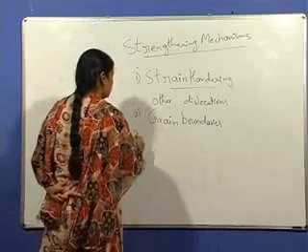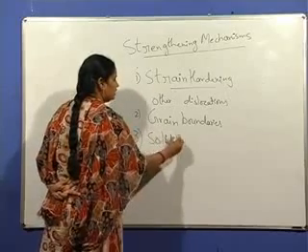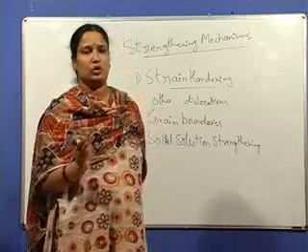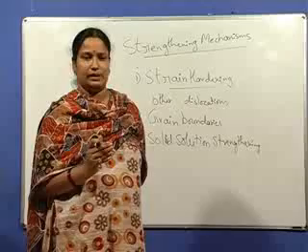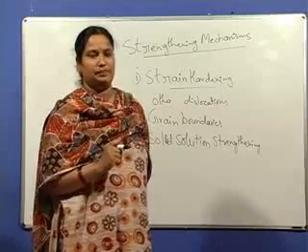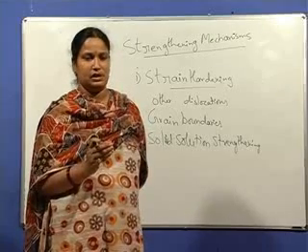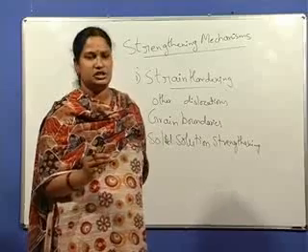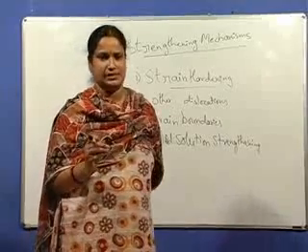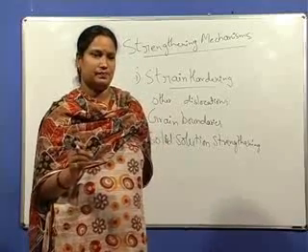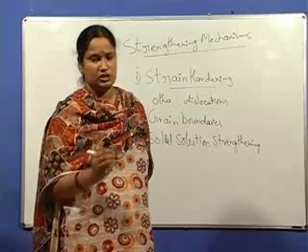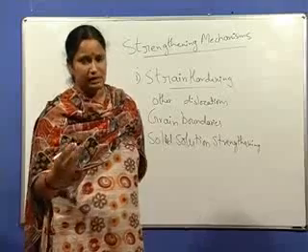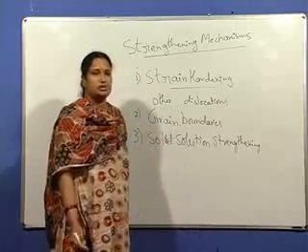Next, the third is solid solution strengthening. Solute atoms, both interstitial and substitutional, also contribute to strengthening. This was also discussed in yield point phenomena. The substitutional solute atoms move near the edge dislocation to reduce the strain energy, and interstitial solute atoms, which are much smaller in size, form Cottrell atmospheres. They occupy the positions below the edge dislocation. How they contribute to strengthening was also discussed. Still more explanation about solid solution strengthening will be given.